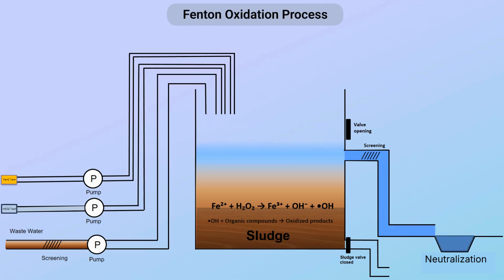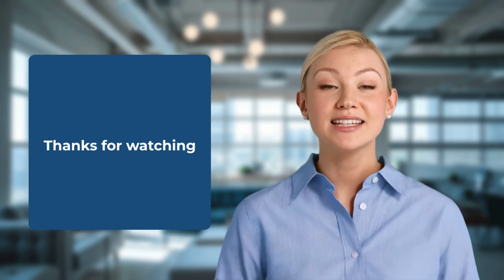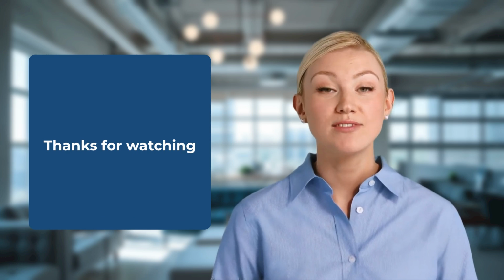The final stage is post-treatment, where the acidic effluent is neutralized to a pH suitable for discharge or further processing. Iron precipitates, mainly in the form of ferric hydroxide, are removed as sludge through sedimentation. And that's how the Fenton process transforms complex textile wastewater into cleaner, safer effluent, one radical at a time.